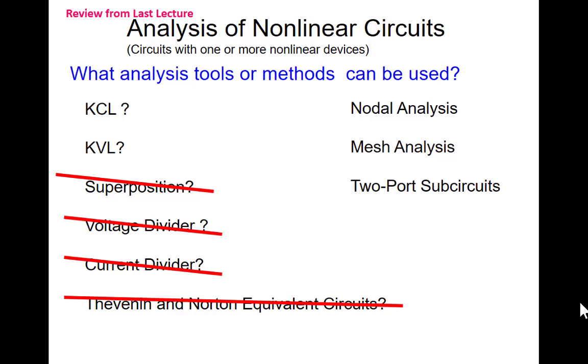And the tools we have to analyze circuits with nonlinear devices are different than the tools we oftentimes use to analyze linear circuits. Some of these things that we derived for linear circuits, like current divider and voltage divider equations and so forth, don't have a corresponding counterpart if the circuit is nonlinear. So you pretty much have to go back to Kirchhoff's laws and do nodal analysis, or I guess you could also do a mesh analysis if you so chose.